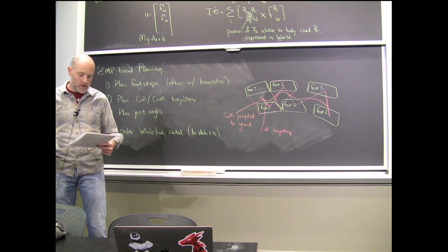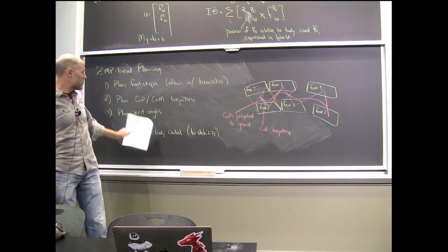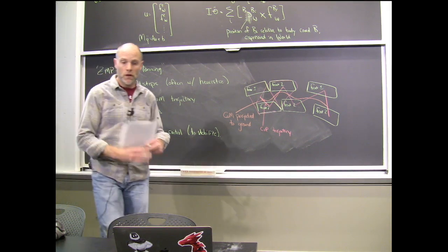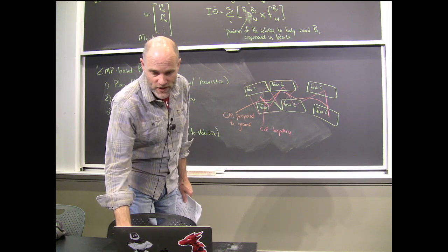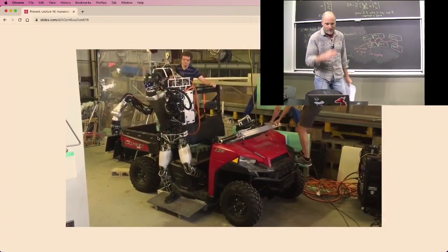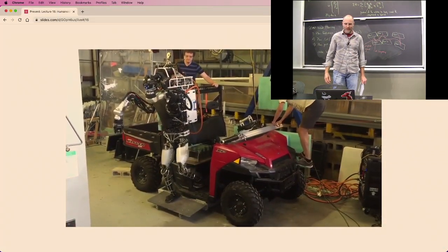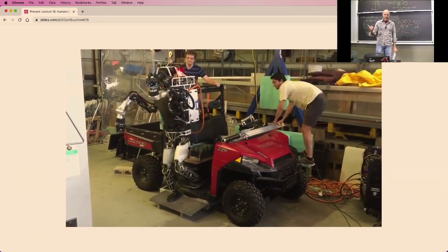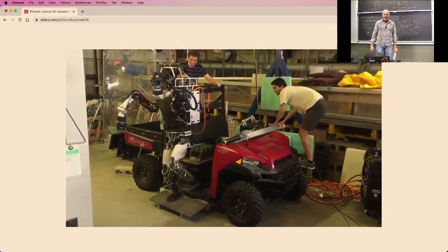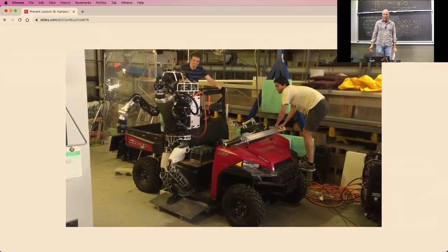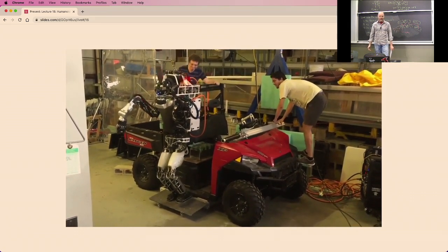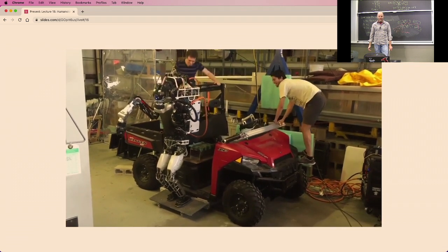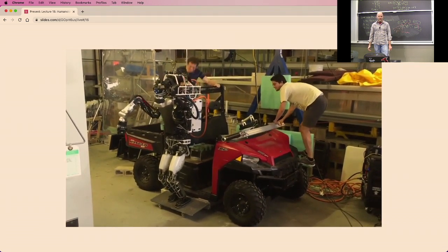Okay, let me just tell you a little bit about the whole body controller that we and other people tend to do for the last step. So this was our favorite demonstration, the hard part of Atlas getting out of the car, and just how robust the controller was. We had a nominal trajectory of the center of mass and a swing foot, and you could do a lot to that robot, and it still would be pretty robust.